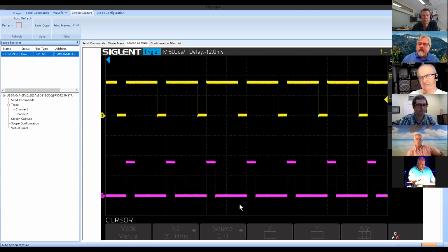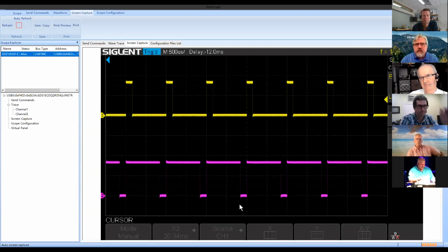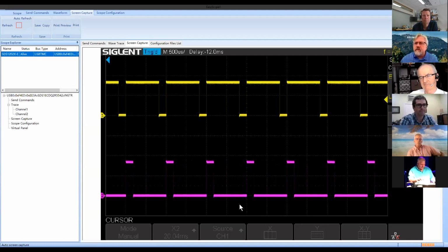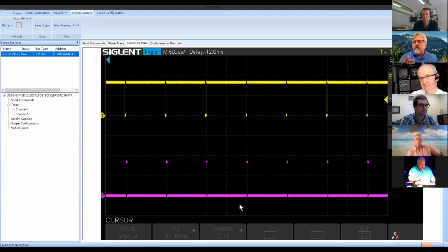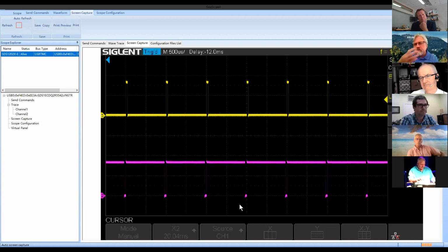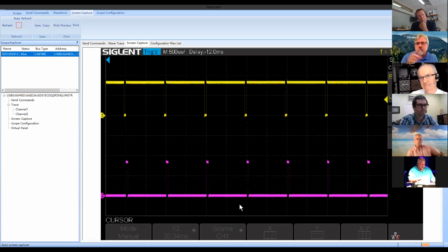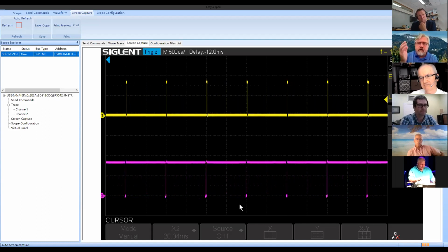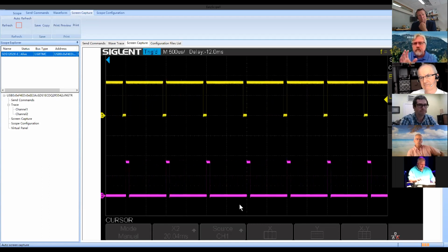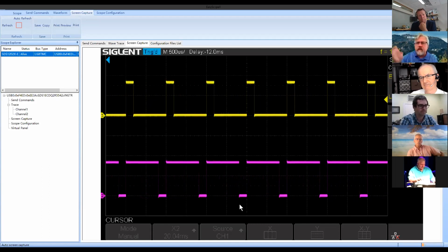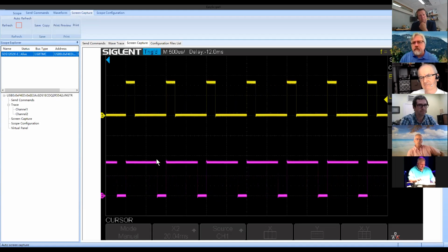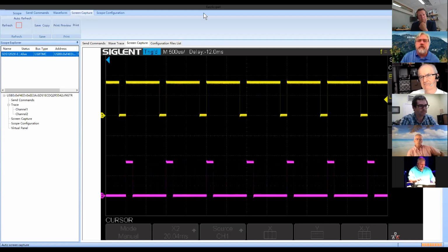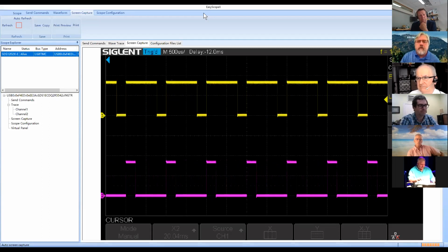I have a thing called, I think it's called JM Easy PWM that's online already. And that will take care of that stuff for you. If you look through that code, you tell it what pin, what your range is, and if you want it triangle or sawtooth, and it will sort it out for you. And then you just write values to it, easy peasy. I brought the code out for this demo so you could see what's going on with smart pins. And I'll just do one thing because I know I'm way over time on smart pins.